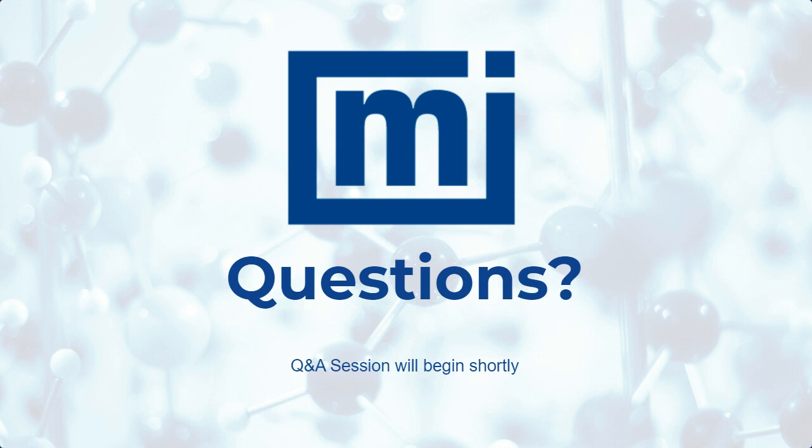I think the biggest contributor to caking is likely to be, and I must point out there's a little bit of speculation here, the contribution from fine particles, which I would expect to be extremely important. If we take the most simple form, a spherical particle, let's say 100 microns in diameter, when these particles are stacked together, we're going to have a lot of empty space in there. And that empty space is surface area of particles that isn't in contact with other particles.